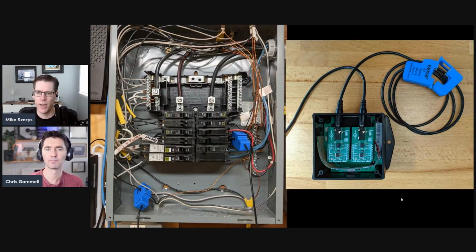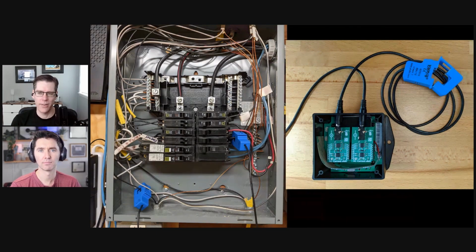Yeah, absolutely. So I have a picture of the actual hardware here. On the right panel, this is the device itself, which we're calling the Aludel Mini. It's one of our standard reference design starting places. Underneath this green board, it has a SparkFun Thing Plus nRF9160, which is a cellular modem. And it's connected up to these two boards, which are ADCs. They're MCP3201s that are reading current clamps. So this blue thing right here is a current clamp that you would put around a power line, and it would be able to read back through the ADC to the cell modem and up to the cloud what kind of current is being used on each of your lines.